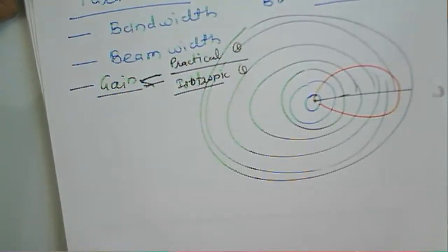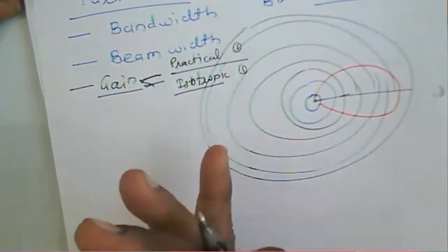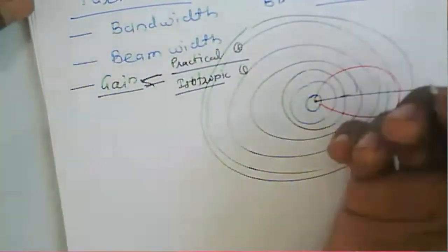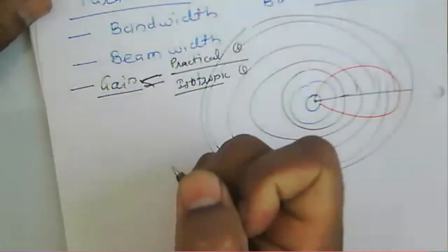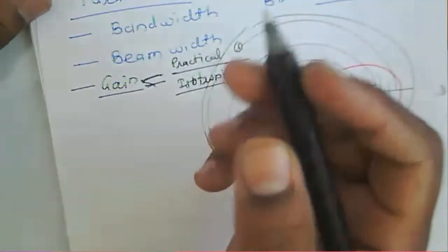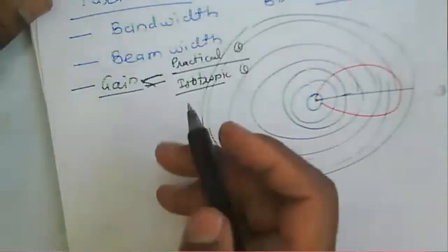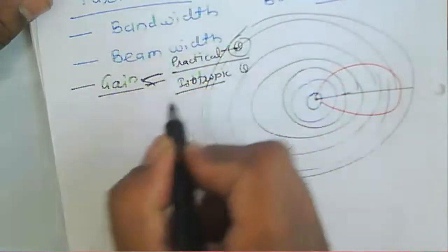So that particular direction is used to obtain the gain of that antenna in the given direction. Take a satellite antenna: it radiates the signal toward the earth, so the directivity is toward the earth, and the signal is transmitted from that antenna toward the earth. So that angle is toward the earth, and that's why it is a highly directional one.